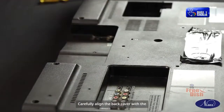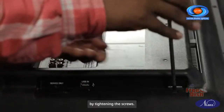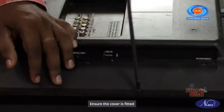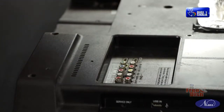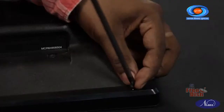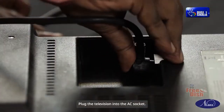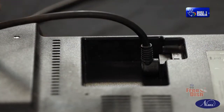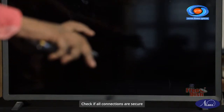Carefully align the back cover with the TV's frame and secure it in place by tightening the screws. Ensure the cover is fitted securely without any gaps. Plug the television into the AC socket. Switch on the TV using remote. Check if all connections are secure and that the devices are receiving power.